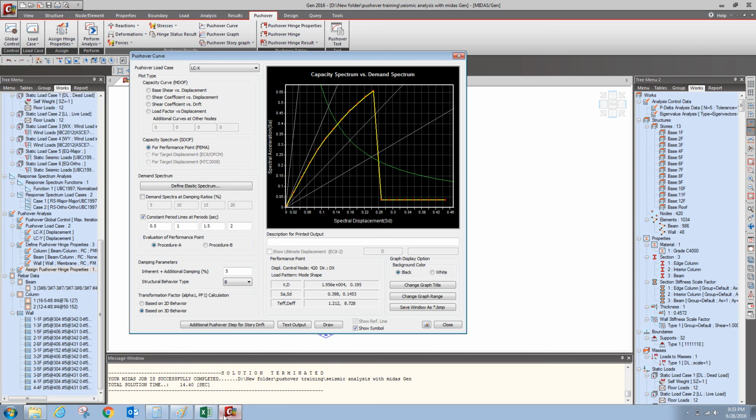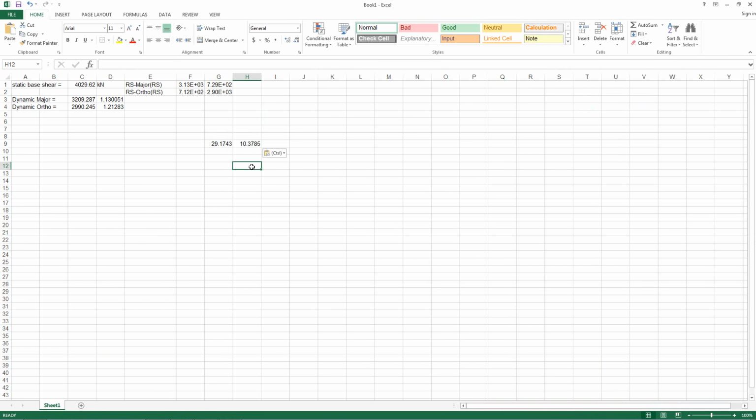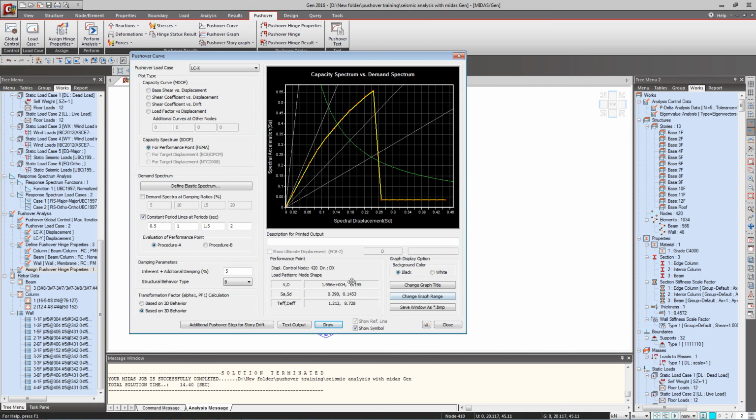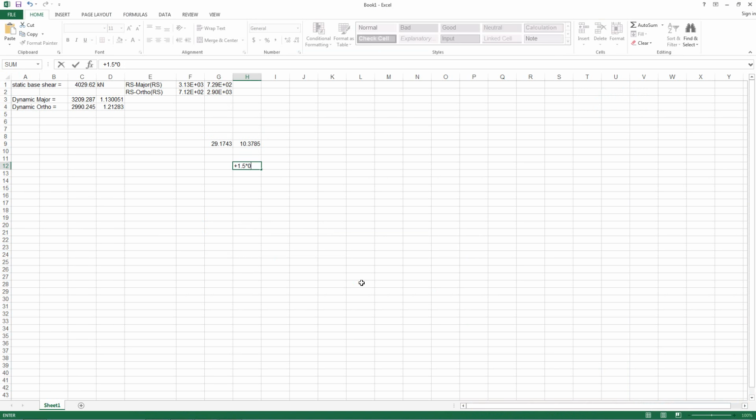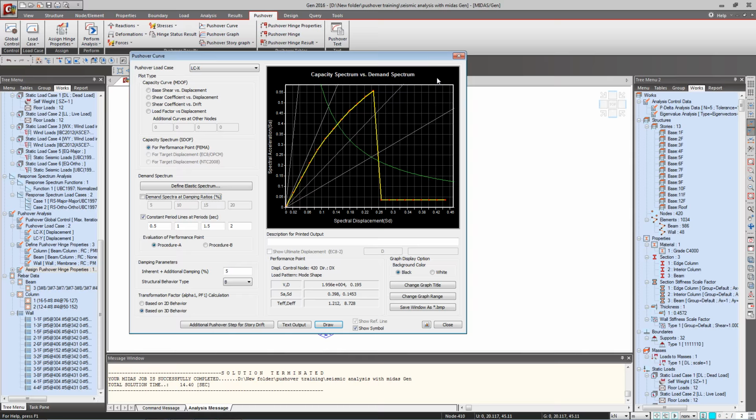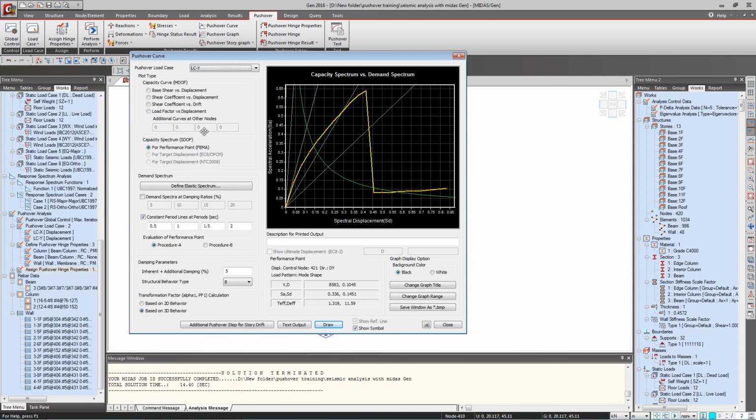I have to increase it by 150%. So the actual displacement which I have to apply will be 1.5 times this particular value, 0.195. So instead of 0.6 meter being the final displacement, I can just use 0.293. Let me check for y direction.